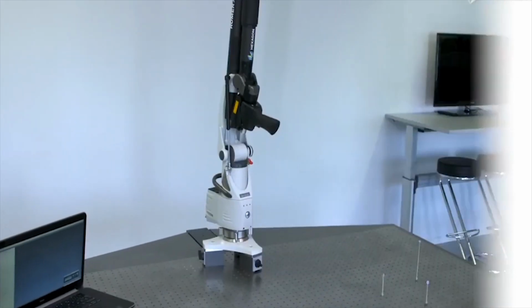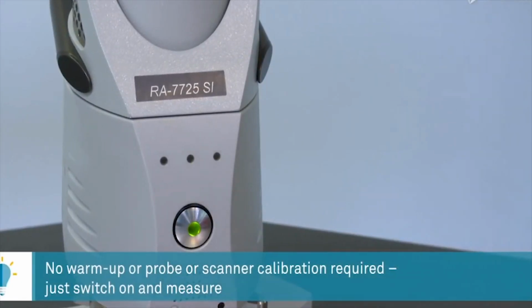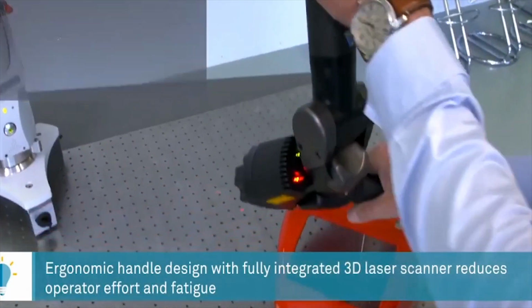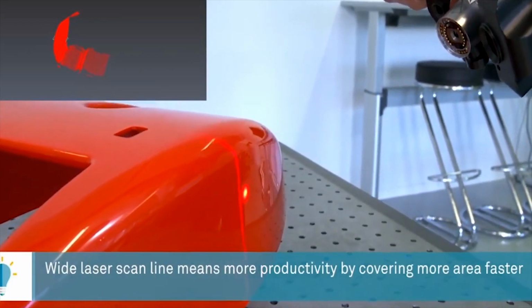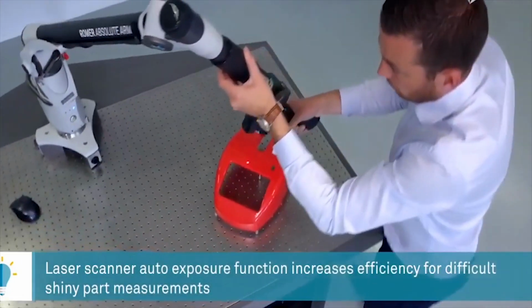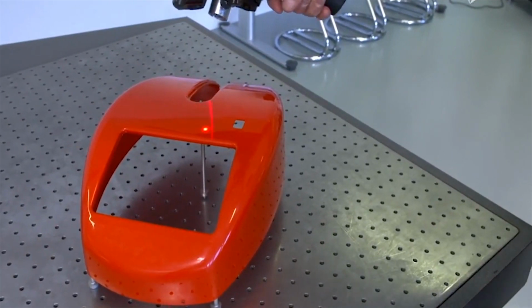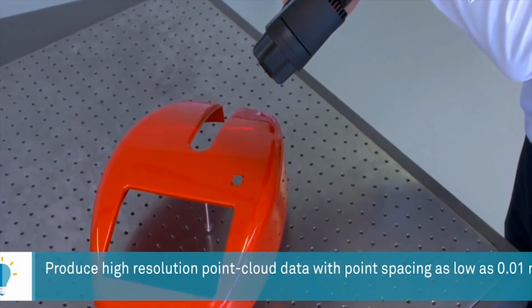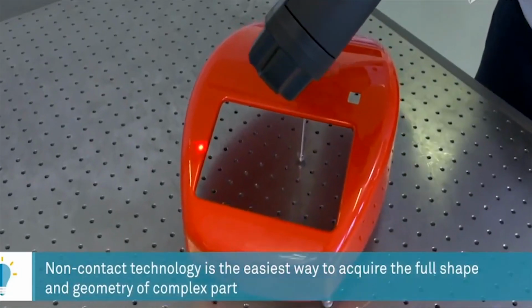Phase 3: Application Geometric Model Development. In the same way that developments in rapid prototyping and tooling technologies are helping to shorten dramatically the time taken to generate physical representations from CAD models, current RE technologies are helping to reduce the time to create electronic CAD models from existing physical representations. The generation of CAD models from point data is probably the most complex activity within RE because potent surface fitting algorithms are required to generate surfaces that accurately represent the three-dimensional information described within the point cloud data sets. Most CAD systems are not designed to display and process large amounts of point data.